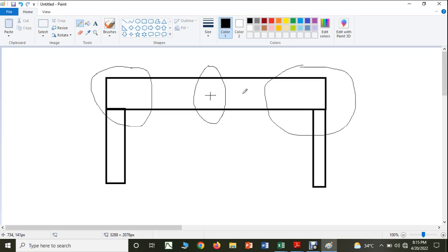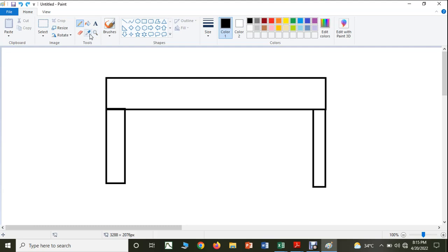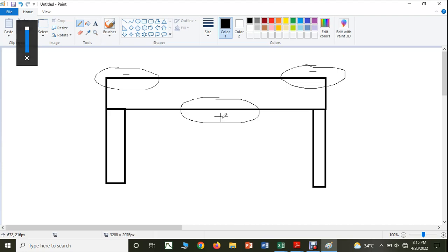And if you want to be still more accurate, the negative bending moment is available at the support, especially at the top of the beam, whereas the positive bending moment is present at the middle of the beam and especially at the bottom of the beam. So these two things we are always supposed to keep in mind.